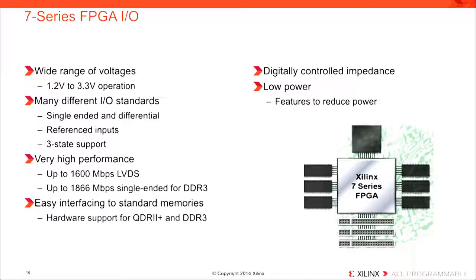You can also configure them as single ended, or you can configure them as differential. And then you can also have reference input. So when you have reference input, you can actually compare with the reference input rather than the bank input, right, which we'll see in the next slide. And then tri-state support. So tri-state is possible for external world, not inside the chip. And then you can use it in differential mode for LVDS type, and then DDR3 compatibility and all that.